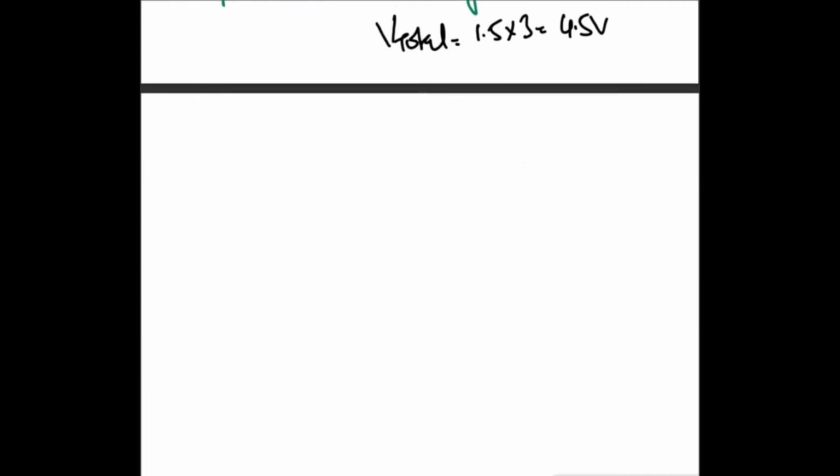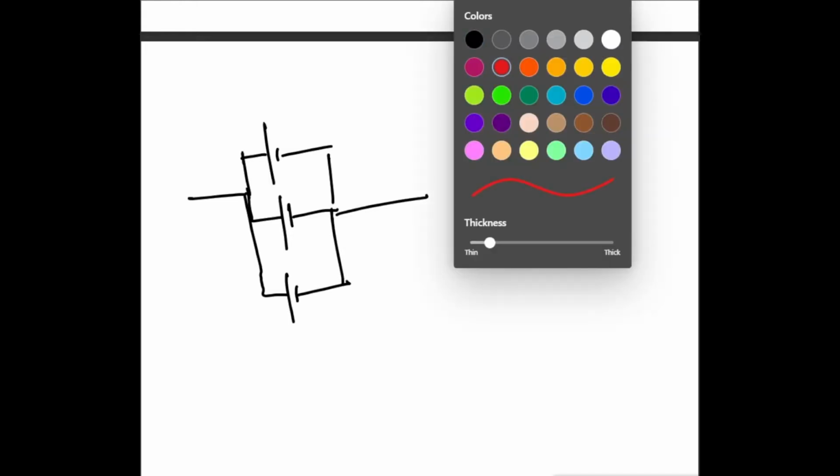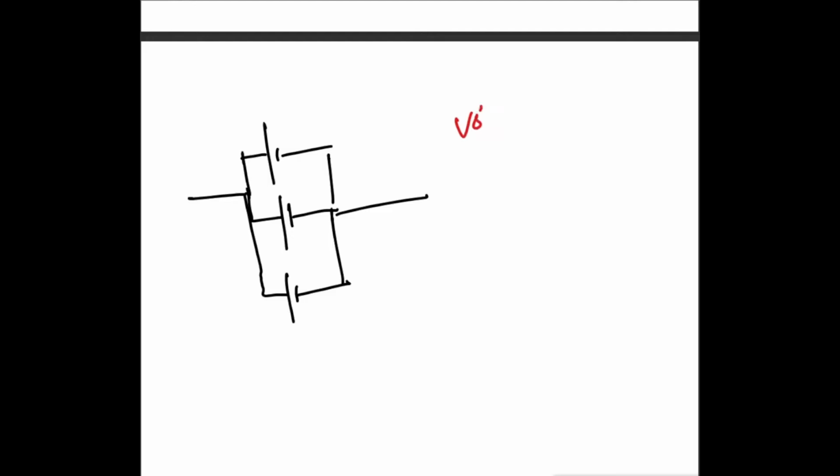And now let's try to connect the batteries in parallel. For example, there are 3 batteries connected in parallel, because the current will now have an alternate choice to go through all these batteries. In this case, the voltage remains the same overall. But then what's the benefit of connecting the batteries or cells like this? I will get to that later. So this is 1.5 volt, this is 1.5 volt, this is 1.5 volt.